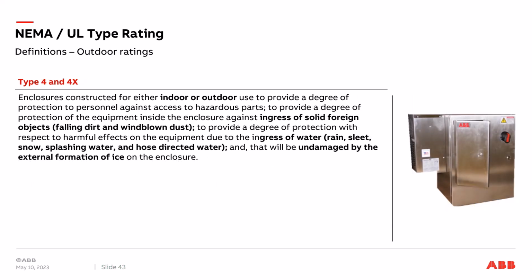Looking at a Type 4 or 4X enclosure, the enclosures are constructed for either indoor or outdoor as before. They will protect you against the ingress of solid foreign objects, falling dirt, wind-blown dust, personnel, but their advantage is protection against the ingress of water, rain, sleet, snow, splashing water, or hose-directed water, and will be undamaged by the formation of ice.